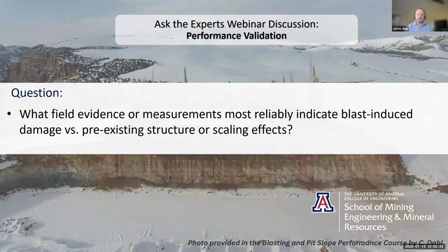And in some scenarios, especially when you're under the water table, pore pressure measurement can become a factor as well, in addition to the other monitoring forms that the group has mentioned. Because if you see unexpected spikes in pore pressure, that could be an indicator that the blast energy isn't exactly going where you want it to. So I think that covers most of it.